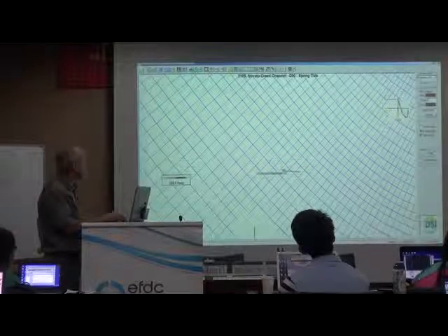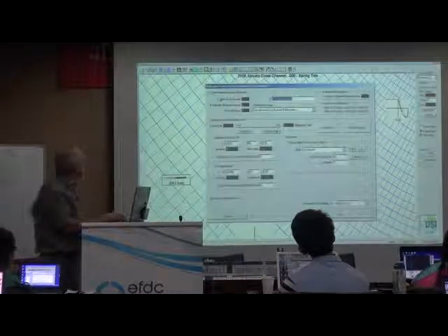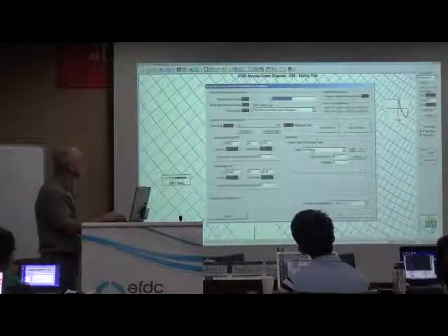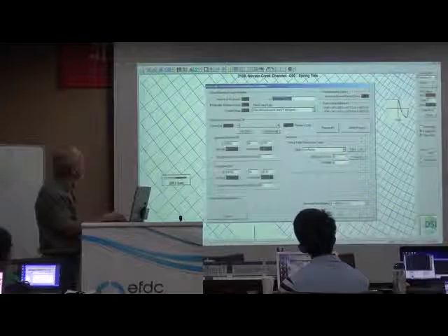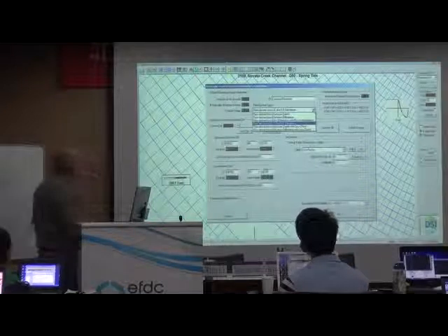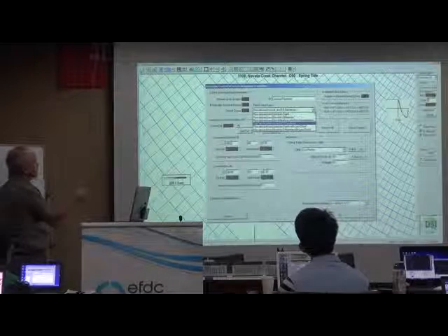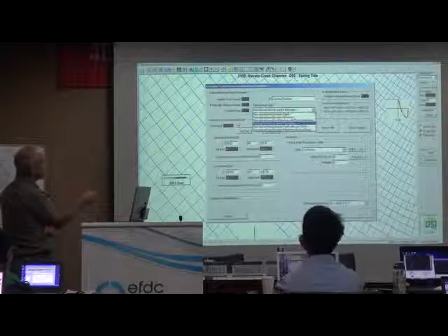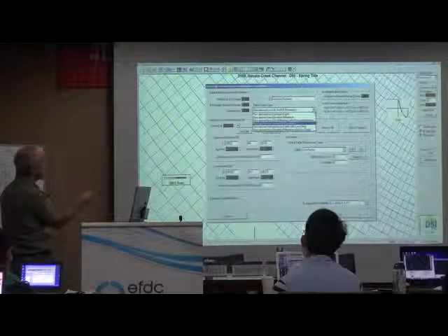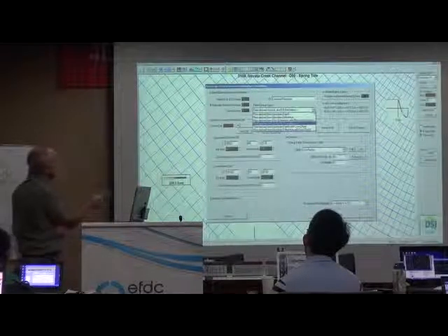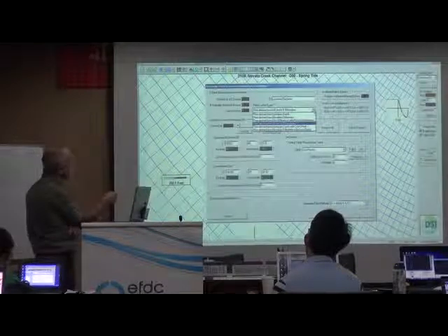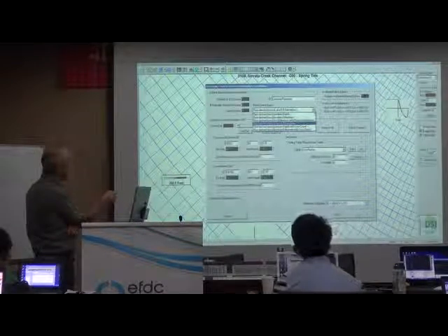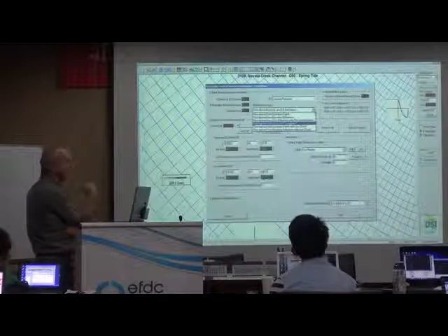Okay, so I go in here to boundary conditions and look in here and edit. So this is the new hydraulic structure boundary condition. It's a much more robust capability. We now have, this is where you set your type of hydraulic structure flow conditions, whether or not it's by upstream depth, elevation difference with flow acceleration, or just upstream, downstream elevations, or this is where you define the low chord options.